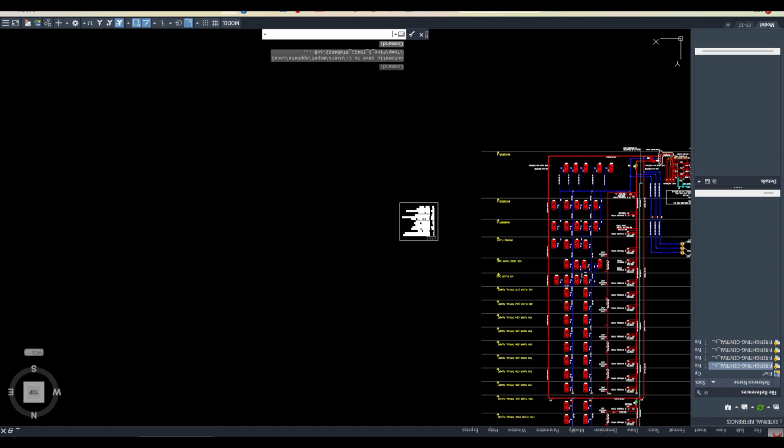Right? Okay, so in fire safety, if you look at the height of the building from the perspective of the fire system, you will always count the landing where you land. You will never walk on the parapet, right? You will always walk on the floor. So basically it is from the lowest grade till the floor level of the roof.